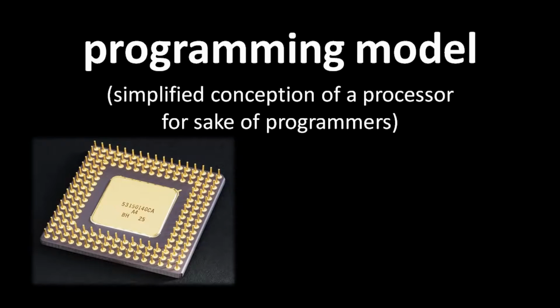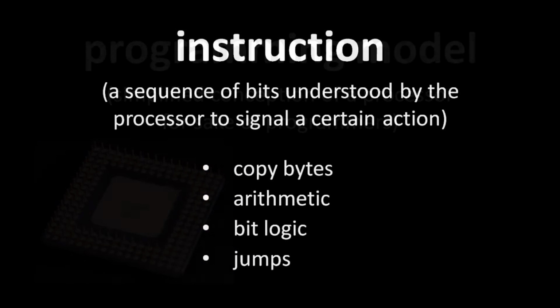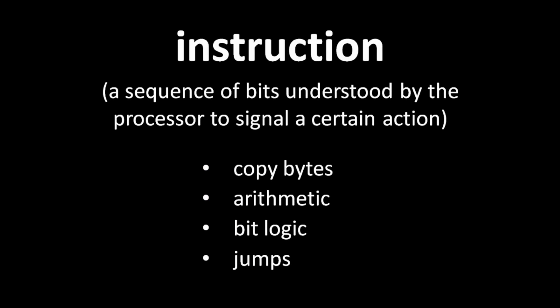So first of all, what a CPU does from the programmer's perspective is execute binary instructions, which are sequences of bits, typically around 8 bits in size on the low end and around 256 bytes in size on the high end, with most somewhere in between. The way to think of these instructions is that the CPU is hardwired to read one instruction after another and hardwired to act upon each instruction differently.